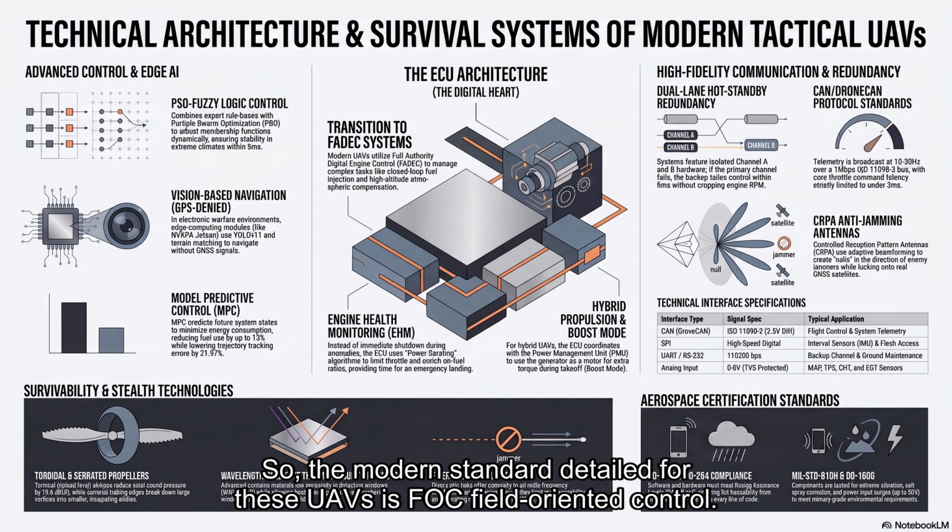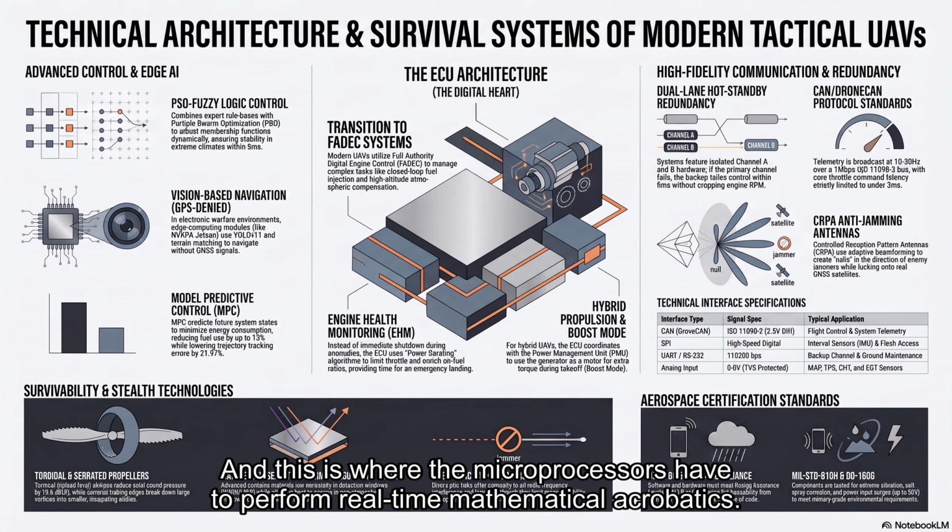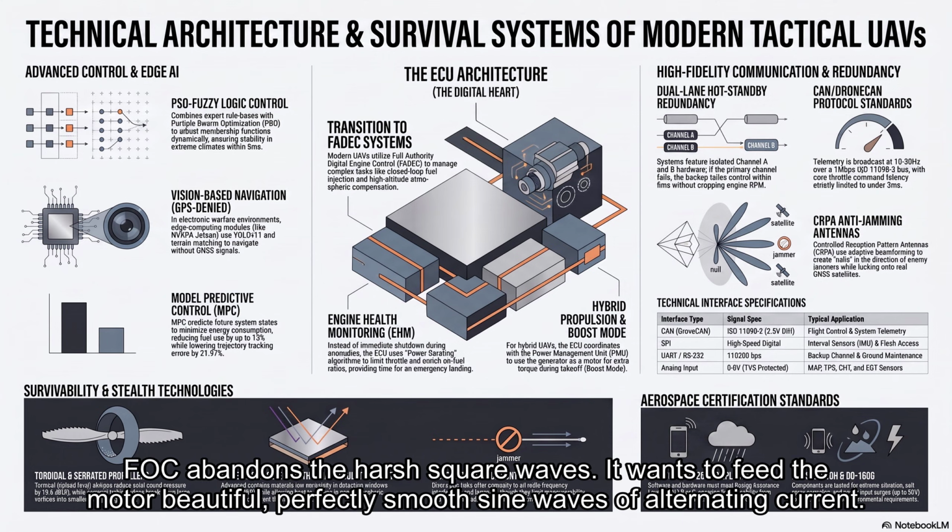So the modern standard for these UAVs is FOC, field-oriented control. And this is where the microprocessors have to perform real-time mathematical acrobatics. FOC abandons the harsh square waves. It wants to feed the motor beautiful, perfectly smooth sine waves of alternating current.